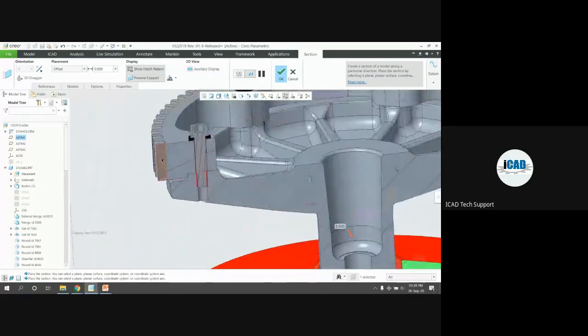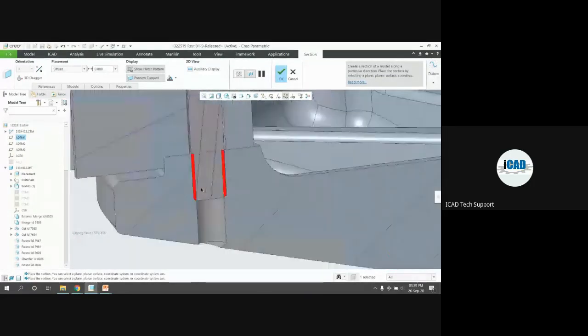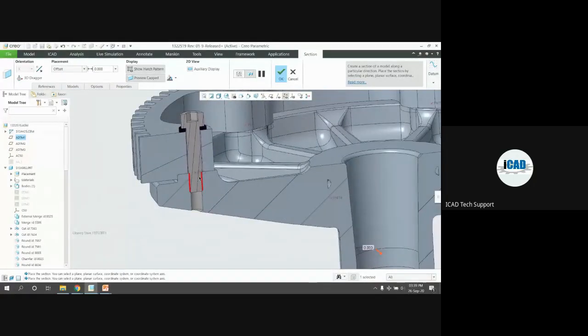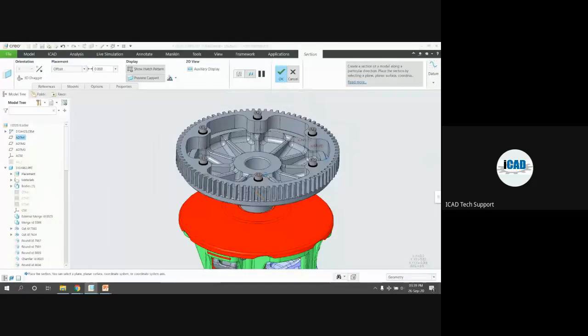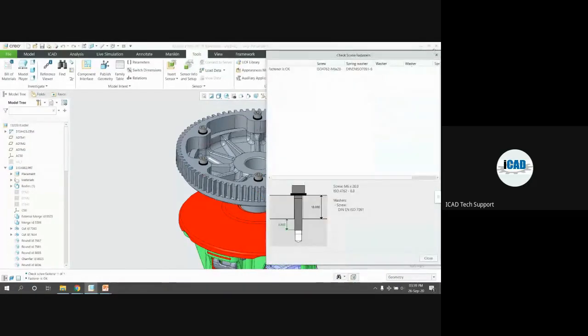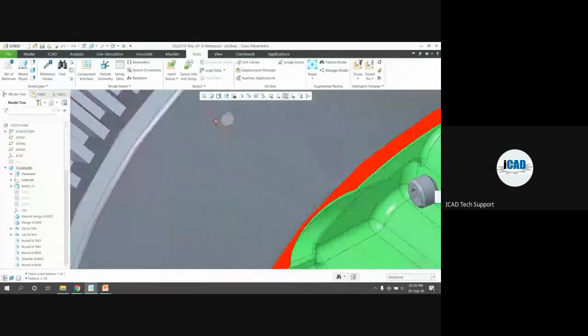You can see the plate thickness we have increased up to 20 mm, and now the screw is engaging with the bottom plate up to 8 to 9 mm. So this engagement is sufficient for this assembly. That's why the fastener assembly is okay, showing in this checkbox. You can see the bottom holes get created.